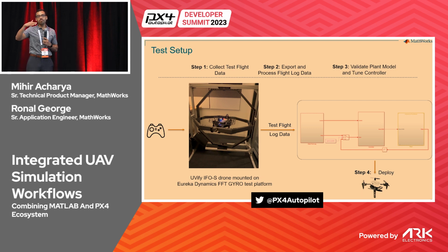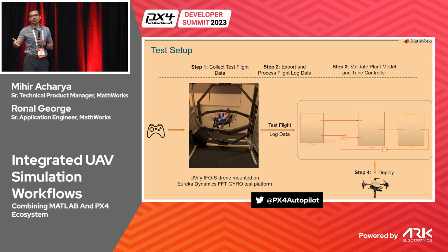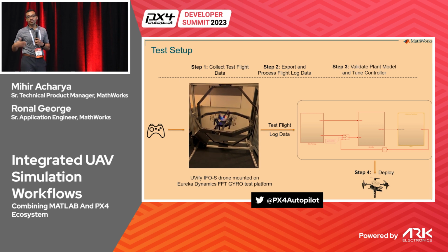I can have experiments with multiple different parameters using the outputs that the simulation makes and the log data. And then I just let it run. It can run for maybe 10 minutes, it can run for 40 minutes. It might get stuck at a local minima, so we'll do a randomized restart. But eventually, I'm going to get a good set of parameters that validates what my log showed to my simulation. So my simulation matches exactly what my log is, which means regardless of the fidelity in which you built your plant, it may be a CAD model, maybe mathematical equations, you know that simulated model is exactly like your actual plant.